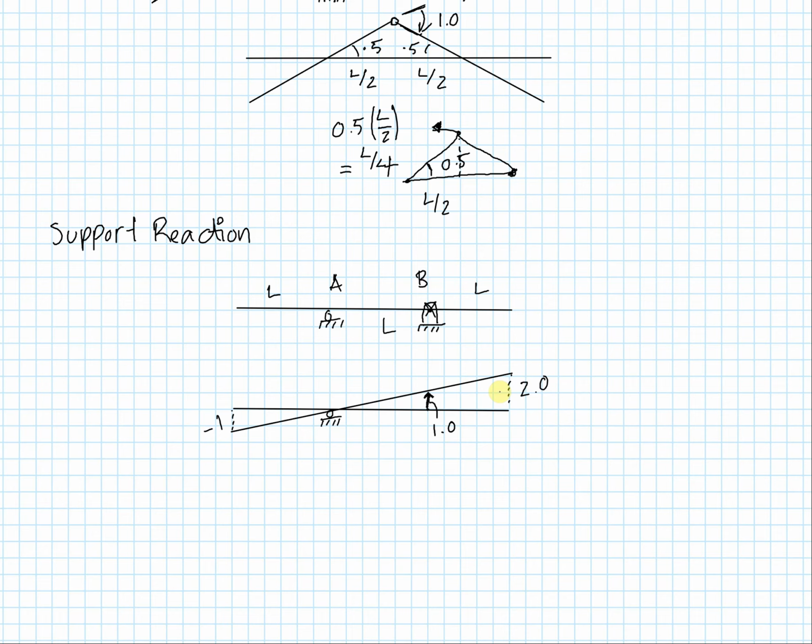And that's really it. I used simple geometry and the relationships, the links that I have, and the vertical deflections that I have, and I obtain all the amplitudes. And so if I were interested in finding the position of a point load that results in maximum reaction at B, it will happen at the very far right, so where we have the 2.0.